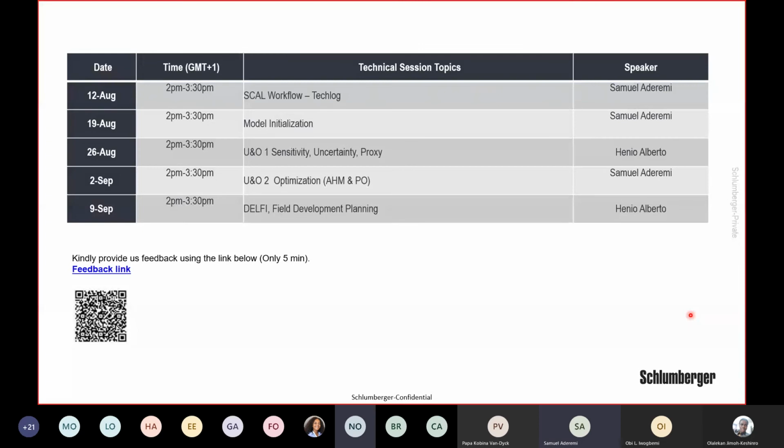There's something that happened one time in one of our fields. We had a reservoir that had a gas cap, so we tried to take a bottom hole sample. But we couldn't take a bottom hole sample because it had a gas cap, the GOR was so high. So when they took surface samples, they went to recombine it.